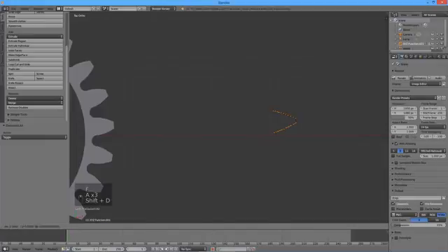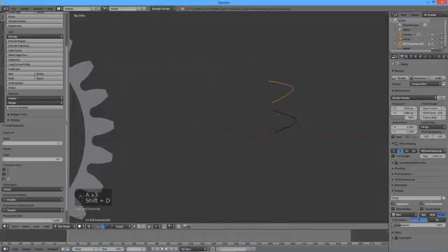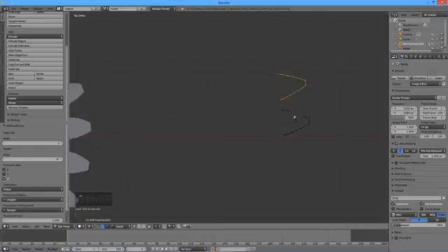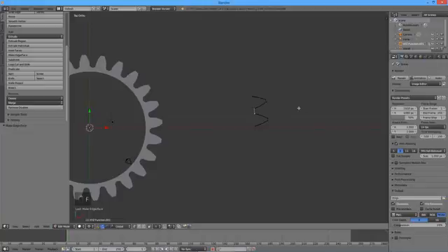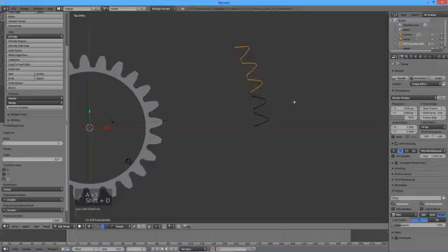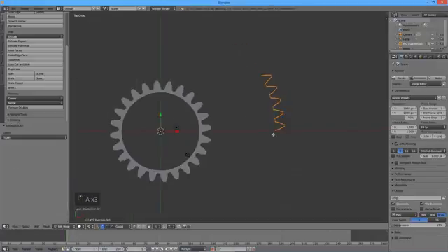Select everything, duplicate and rotate around the Z-axis by 6 degrees, which is 360 divided by the number of teeth in the ring gear. This time, do not use the spin tool to connect the two adjacent teeth. Just connect them with an edge by pressing F. Select, duplicate and rotate by 6, 12, 24 degrees, and so on until the entire outline is completed.